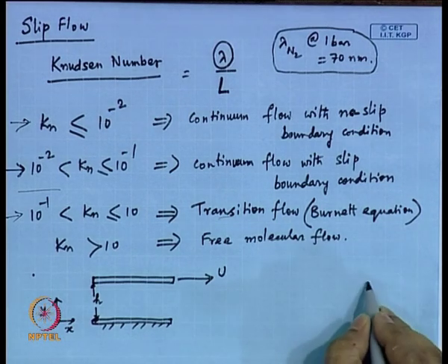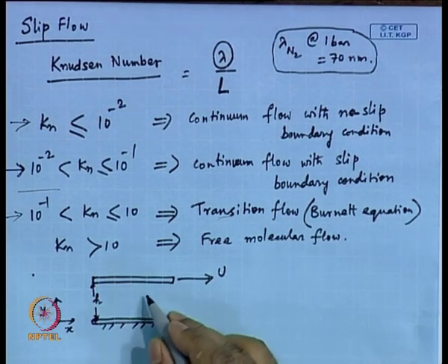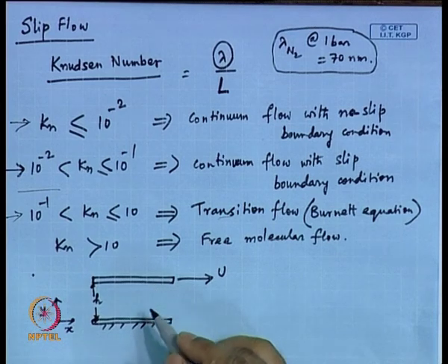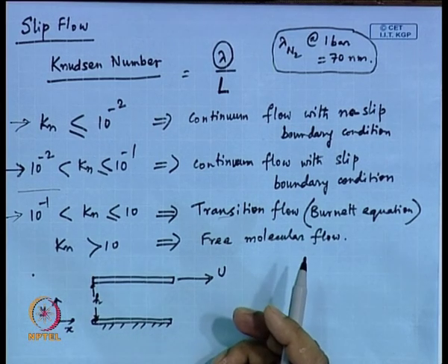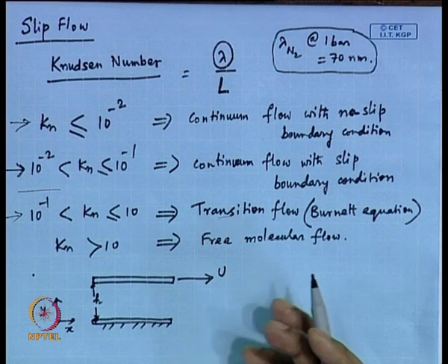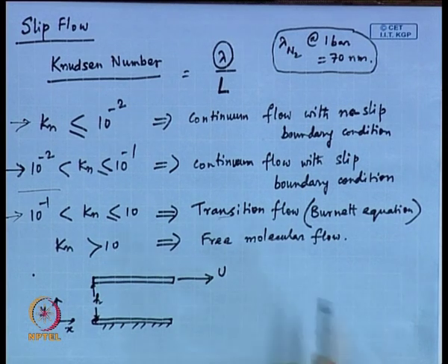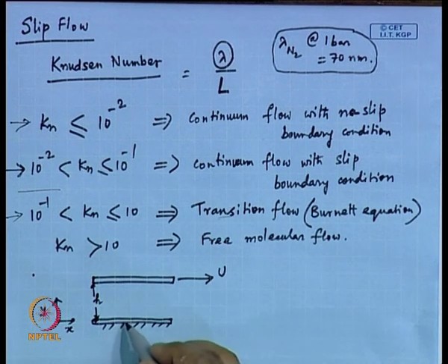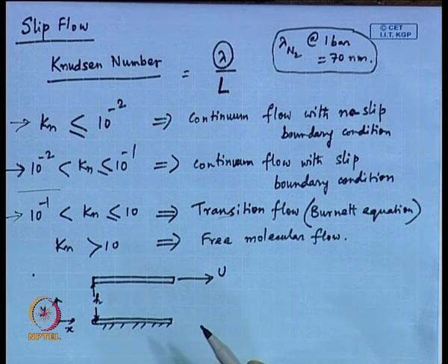There you end up with the velocity changing linearly with distance. To come to that, you make certain assumptions. If you start with the Navier-Stokes equation, all the components are gone and you end up with only one term, so you get the velocity changing linearly with y and no variation in velocity in the x or z direction. You are familiar with that part.